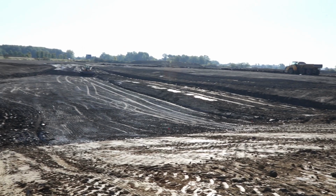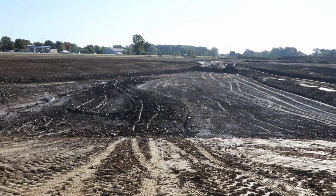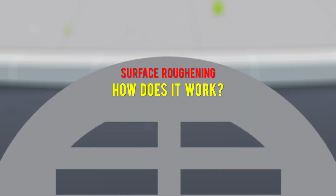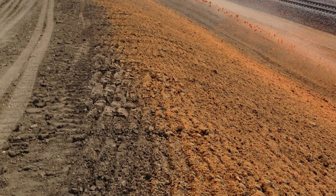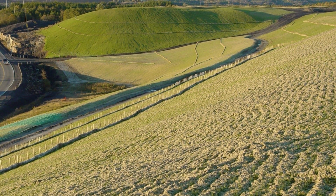Surface roughening. What is the practice? What does it do? Surface roughening is a measure used to create an intricate pattern of ridges and valleys on slopes until seeding can occur. How does it work? It protects the soil surface from erosive forces, traps eroding soil particles, enhances vegetative establishment, but not if the surface is smooth and hard, reduces runoff velocity, and increases infiltration.